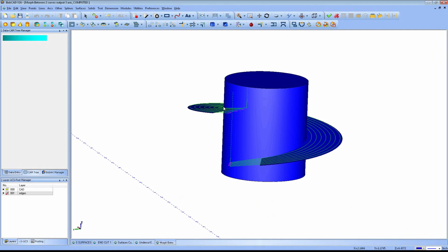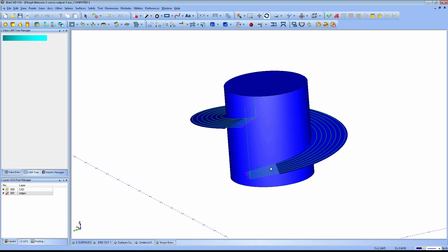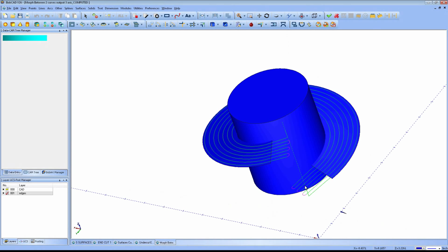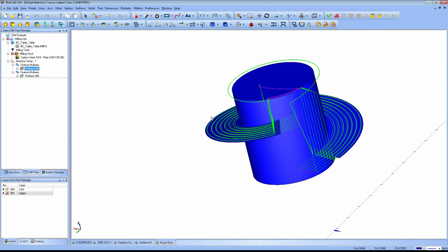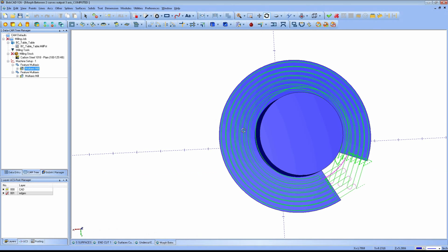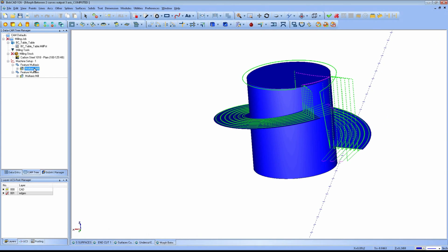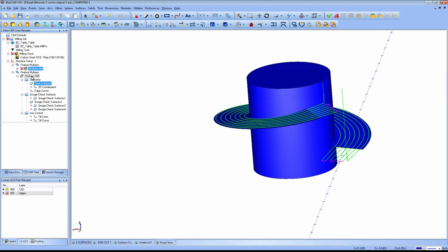This one, we can actually toolpath right off the part, and we can get the toolpath to be compensated for whatever flat bottom or ball tool that we're using. Very easy to do, and you can see how I was able to extend those over as well to make sure that they come in cleaned. Again, to do a toolpath cut like this, we have a couple different ones here. If I unblank this, you can see I did another one around the top, kind of like a step down as well. We'll just leave that blanked out for now. And this is the one that I wanted to look at here.